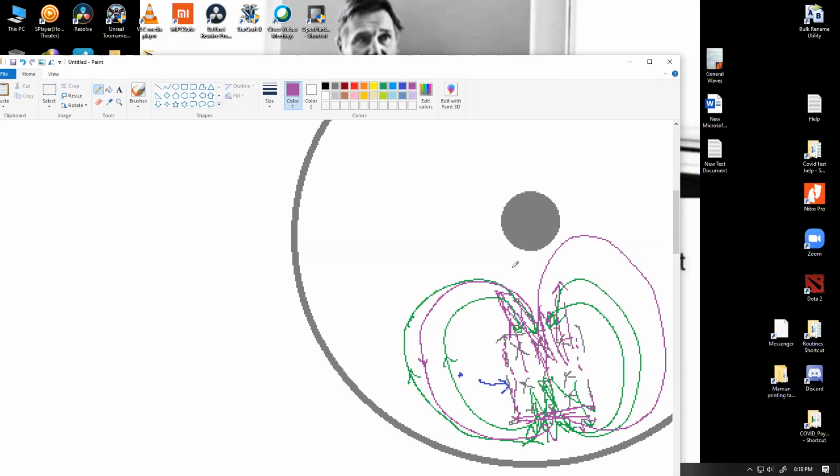This current is what we call eddy current, and the braking system that I just discussed is called eddy braking. It is more applicable to vehicles which move really, really fast. For example, a very common use for eddy braking is in bullet trains in Japan or other places in the world where they have electric trains, because at extremely high speed, friction brakes don't work very well.